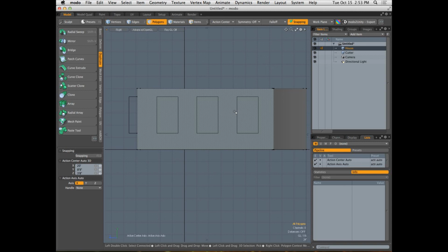It's really neat. In a lot of applications, figuring out the center point of a very specific piece of geometry is a challenge, okay? In Modo, it's really easy if we use the work plane accordingly. The work plane is more than just an interactive snapping guide. The work plane, as you guys have experienced earlier, is a tool that allows us to create geometry orientated along the axes that we need them to be initially. But we can also use the work plane as an element to help us position objects within the scene. The work plane can move, and we want it to move, okay?